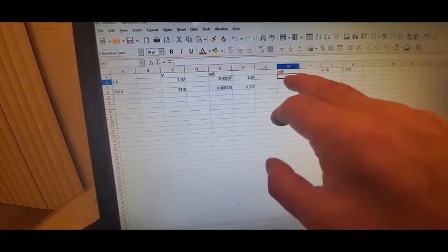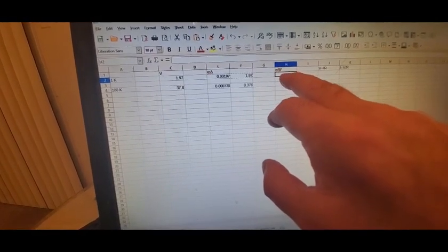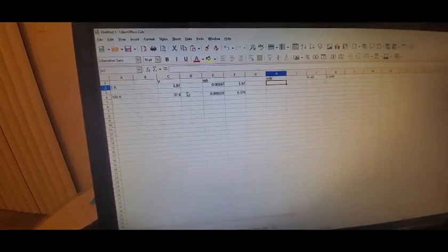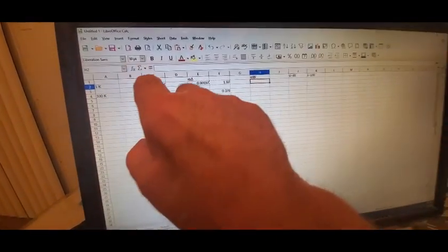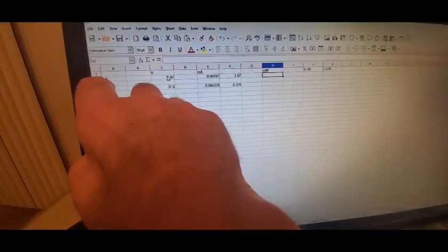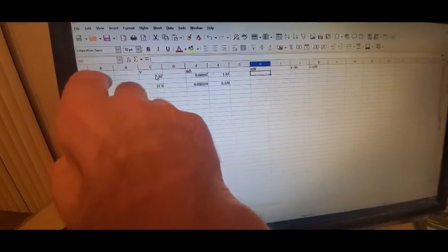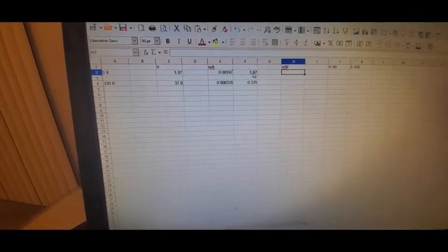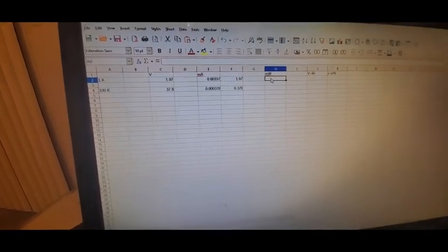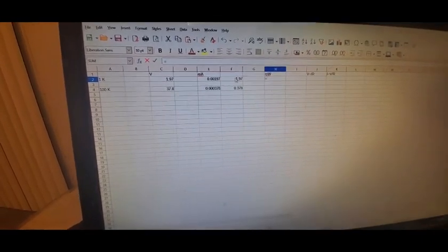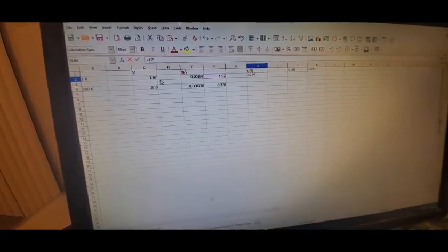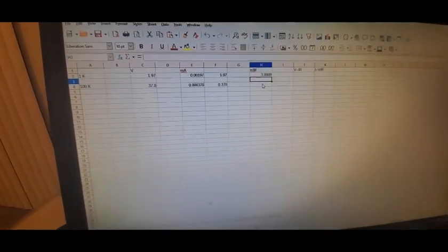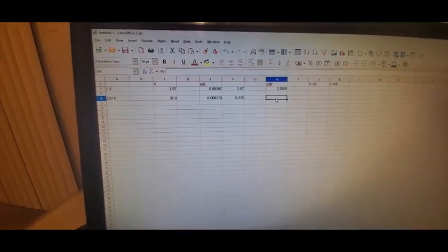And if we talk about power out, which is milliwatts, then that's going to be equal to voltage times current. Now these numbers match, 1.97, 1.97, because it's multiples of 10, 1K, 100K. If it was a 2.2K ohm resistor, they wouldn't match. But so you have 1.97 milliamps times 1.97 volts, you're putting out, let's round it up, 3.9 milliwatts.